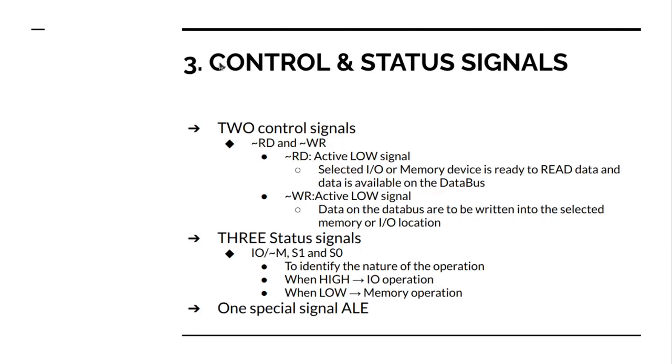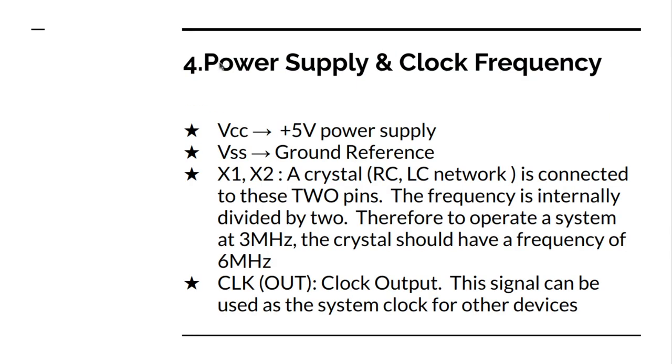So what are these? X1 and X2 are pins to which a crystal, RC or LC network is connected. The frequency is internally divided by two.